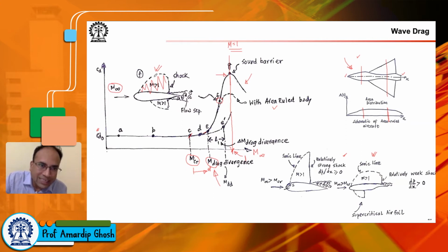So you see that we get this extended area of supersonic flow terminating in a shock wave. We have adverse pressure gradient causing flow separation. On the bottom portion as well, you can have pockets of supersonic flow terminating in shock waves that impose adverse pressure gradient, causing flow separation from the bottom surface of the airfoil as well. So this is just an experimentally determined flow field of what happens on the airfoil in terms of the shock wave and flow separation, etc., at a point above the drag divergence Mach number.